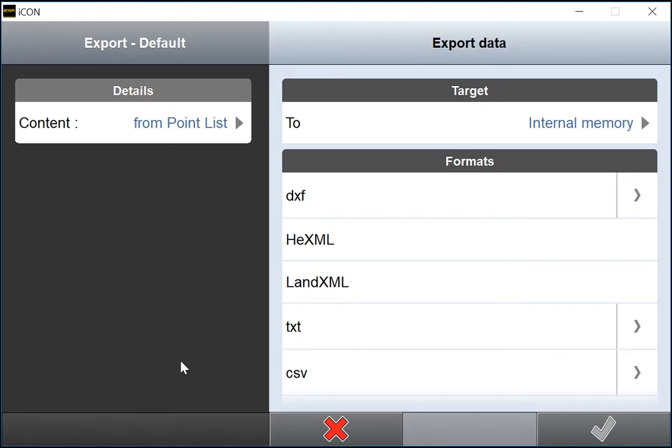You do not have to highlight any points blue in order to export from this point list. By clicking export, the software is going to export all the points you have on your list anyways. I use the map selection method to select points for this reason. I only want to export the points I'm concerned with, and map selection allows me to choose those points specifically. By clicking export from the toolbox, I'm taken to the screen that allows me to choose the target location where the point will be saved and the file format they will be saved in.